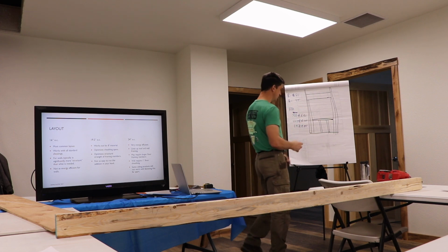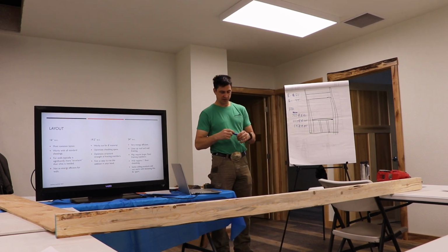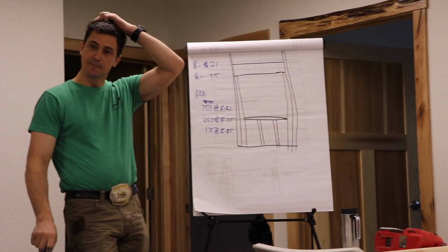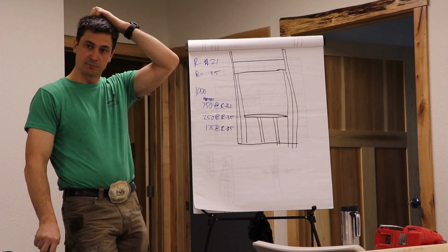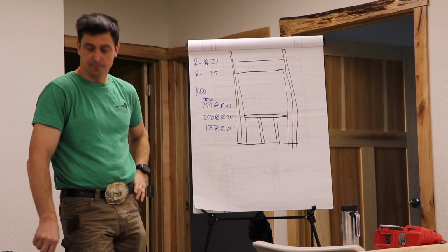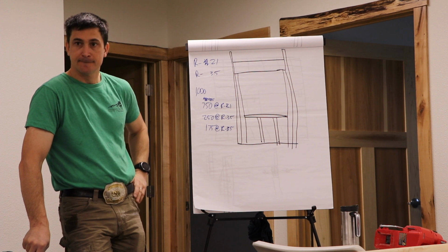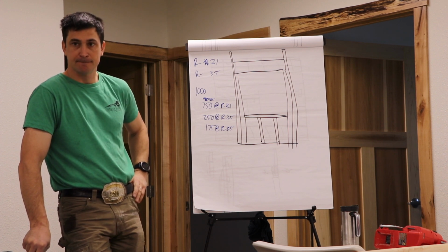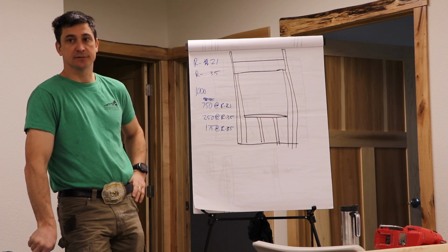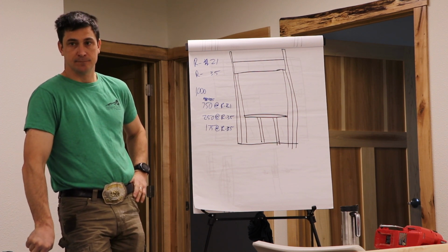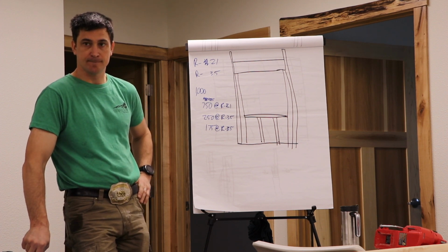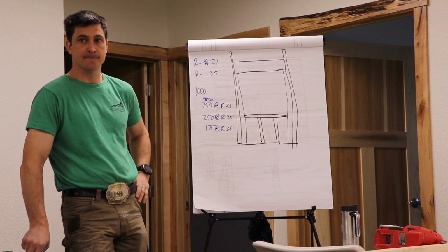So all of a sudden that house that's framed at 24 inches on center gets a nice boost in performance. They were talking about that, the thermal bridging through the wood. Even though your cavity is R21 and the board is 3.5, it's basically taking the 3.5 away from the 21, so you have a total of 17 and a half. Yeah, with less wood material, you have an overall higher R value.